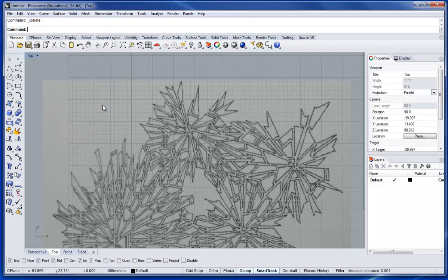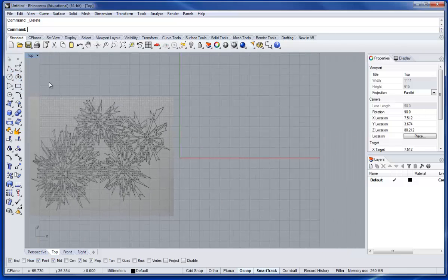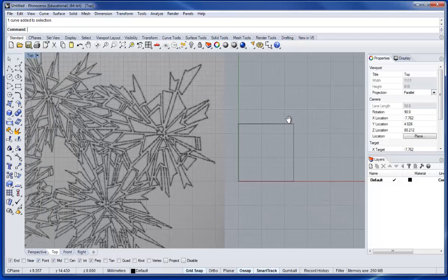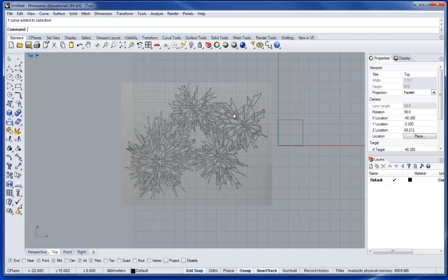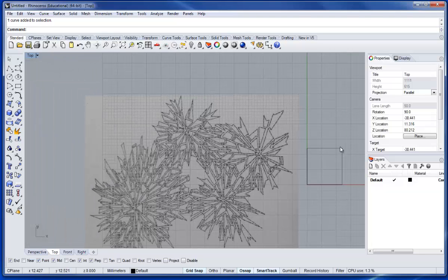Okay. As we start to get into this and start to draw, the first thing we're going to look at in the assignment is that this eventually is going to have to fit into a 12-inch by 12-inch module here. So I'm going to go ahead and turn on my grid snap so I can snap to my origin. And I'm just going to type 12, enter 12. And so that's the size of the unit here that we're going to be trying to fit to. Obviously I'm going to be drawing much larger than the actual piece. That's okay. We'll utilize the scale tools to scale down the drawing once we have it set up. And that has advantages and disadvantages. You want to pay attention to the spacing of your parts so that you don't accidentally make something too thin when you scale it down.